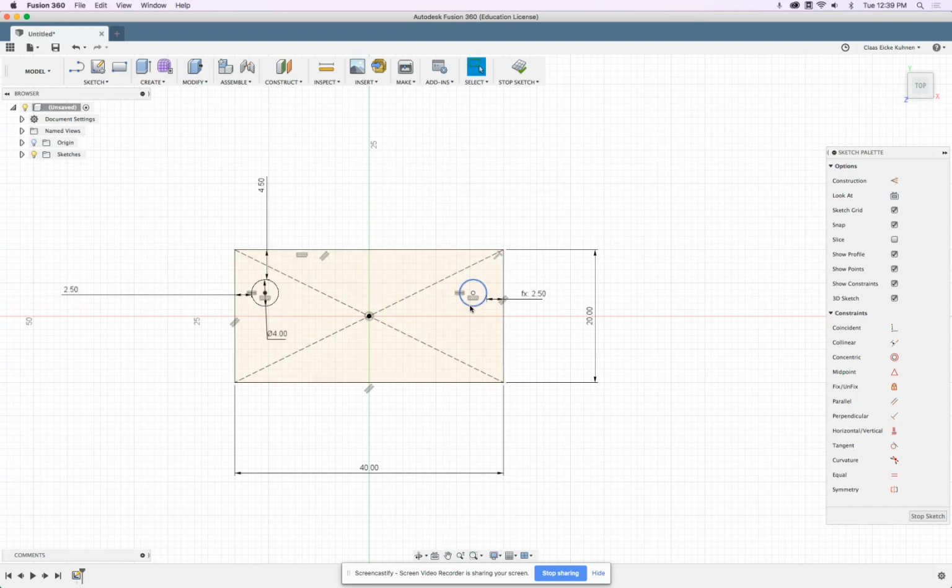In class yesterday, it was brought up, well, how do we do mirror actually inside the sketch? I can show you this too. I will draw a line on the grid along the X line, the Y line. And then I make sure that this point is vertically aligned to the center point. So this line is really at the center. And then I could go mirror and say this circle, a mirror along here, there. Boom. It does it. Works pretty good.